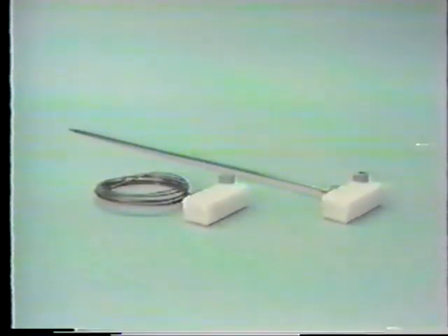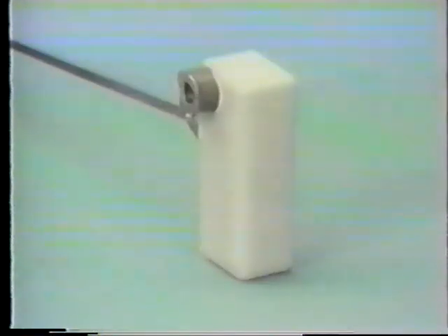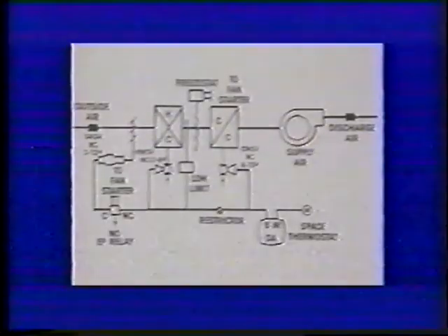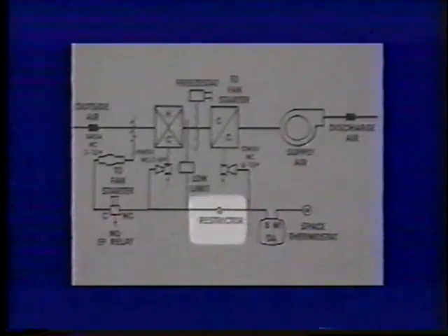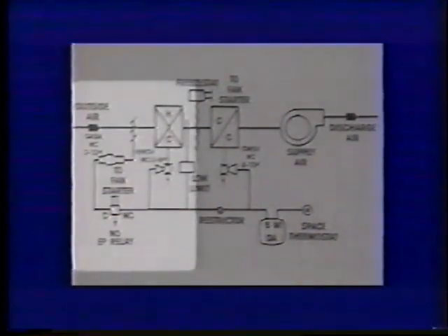The last device to be covered in this section is the airstream temperature controller. Designed primarily as a low-limit thermostat for use in unit ventilators and central fan systems. This controller is a direct-acting, one-pipe, bleed-type device used to modulate a branch line pressure as a result of temperature changes at the sensing element. In this application, the airstream temperature controller is used as a low-temperature limit located downstream of the heating coil. The restrictor in the airline limits the amount of airflow to the downstream devices, the airstream temperature controller, the hot water valve, and the outside air damper.